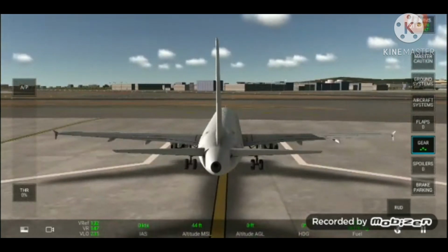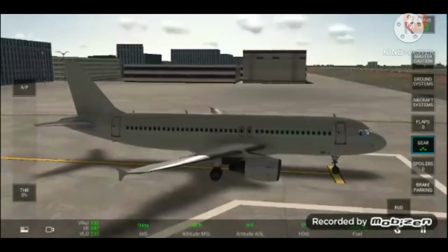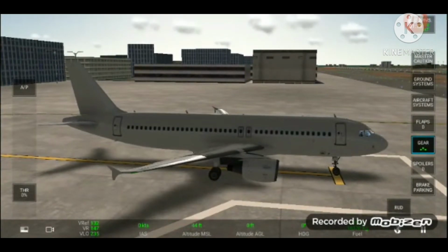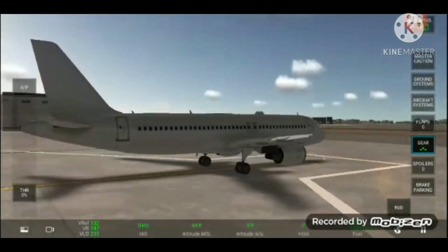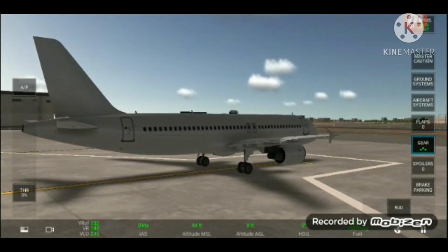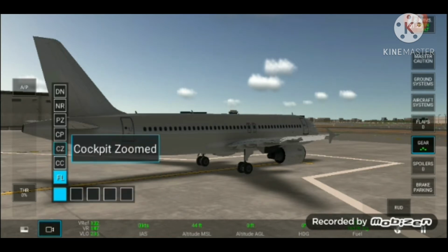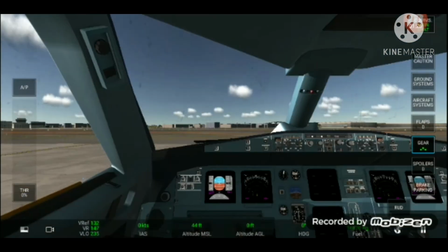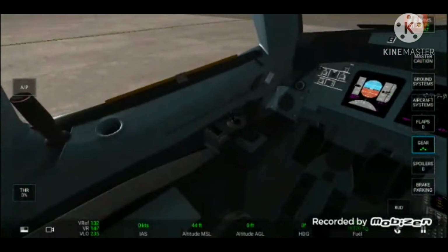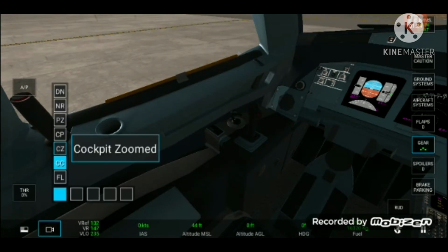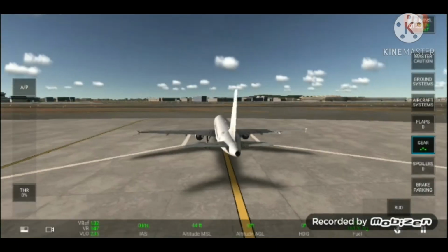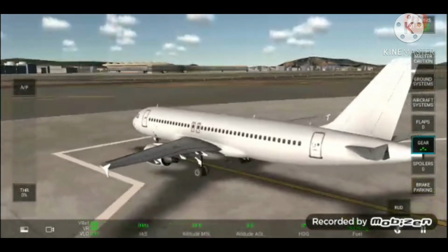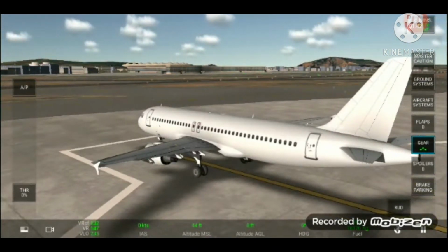When the pilot moves the joystick towards the left, the left aileron goes up and the right aileron goes down. It happens opposite when the pilot moves it towards the right. A raised aileron reduces lift on that wing and a lowered one increases it, so moving the joystick towards left causes the left wing to drop and the right to rise. This causes the aircraft to roll towards left and begin to turn to the left.